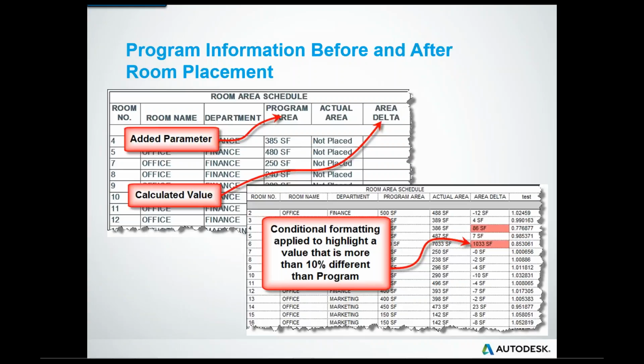In our class, we have a room area schedule. I got to tell you, folks, this is awesome. When I show this to my class, it's really, really nice. I know you can do a regular schedule in AutoCAD, but having the ability in Revit, you'll see in the bottom part here that's in red, it'll automatically calculate my square footages for all the rooms.